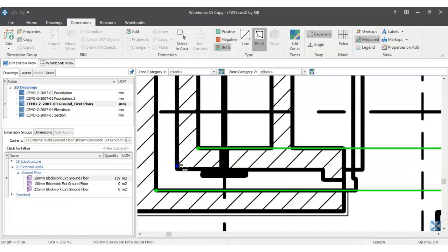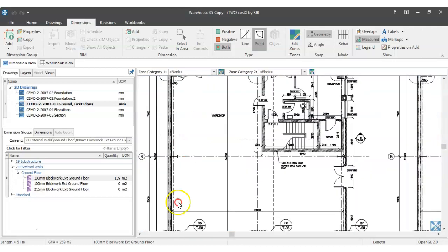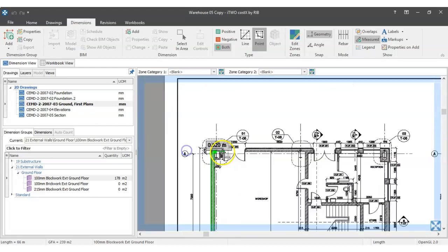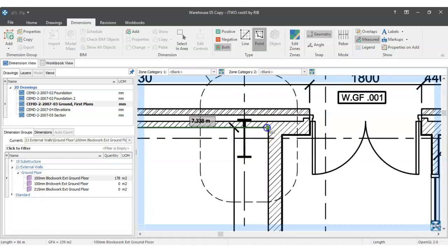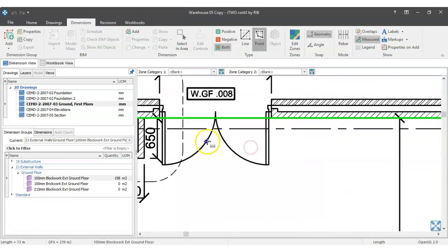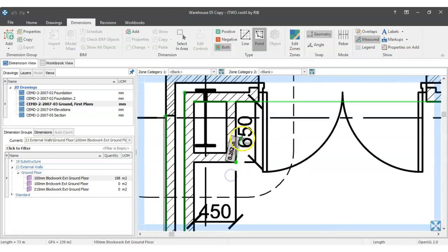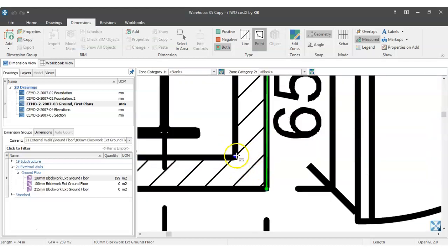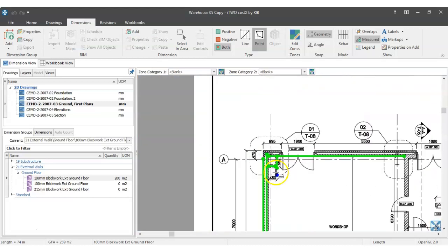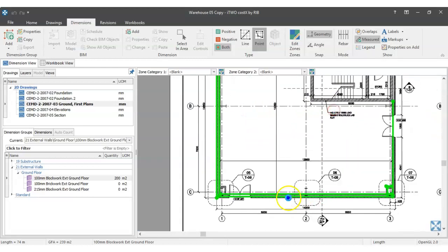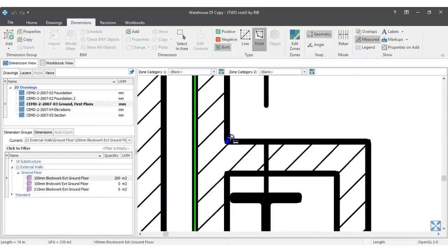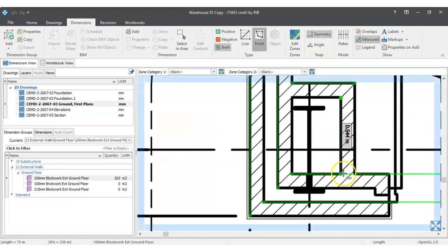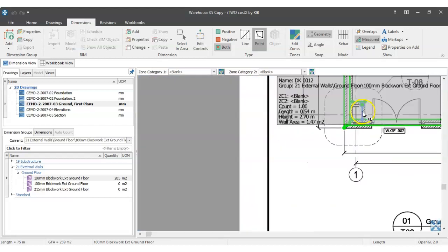And then going from the outside here up all the way to right there, and from here to here, because this is where the 215 begins, and then make sure I've got my corners measured here, right there to there, and then because I don't want to double measure this corner, I'm going to click from there to there. Okay, so that should cover me. Just checking again, have I missed anything? I missed this little corner here. So this is 100mm block work that goes around, click again, that goes around the stanchions here on the ground floor.